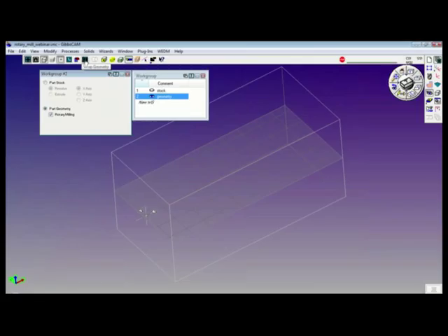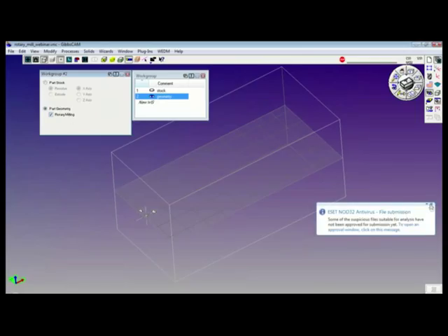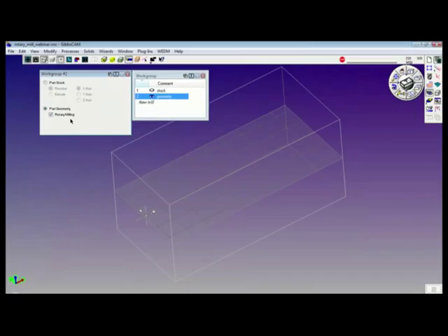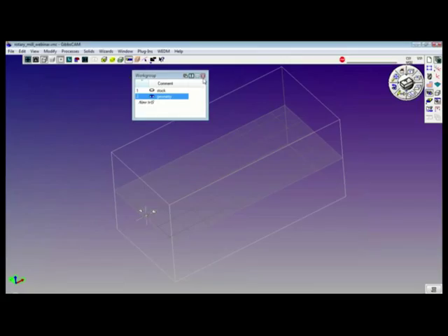When I use this tile, I can actually wrap the geometry around the cylindrical shape or flatten it out. If this checkbox is not checked, this tile will not do anything for you. So we're creating part geometry in rotary milling mode. If your installation does not show rotary milling, you may not have rotary milling on your licensing scheme. Okay, we'll close this up and close this window up.